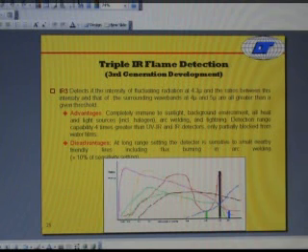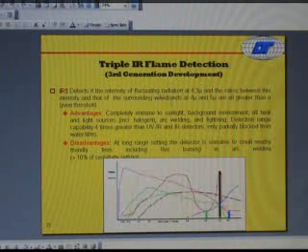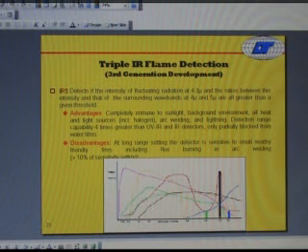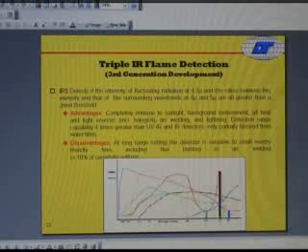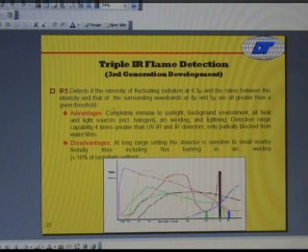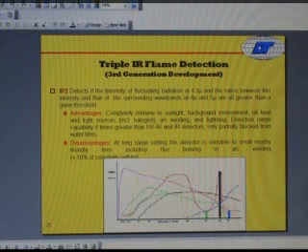It detects if the intensity of fluctuating radiation at 4.3 micron, and the ratios between that intensity and that of a surrounding wave band of 4 or 5 micron, are all greater than a given threshold. Advantages: completely immune to sunlight, background environment, all heat and light sources, arc welding, and lightning.